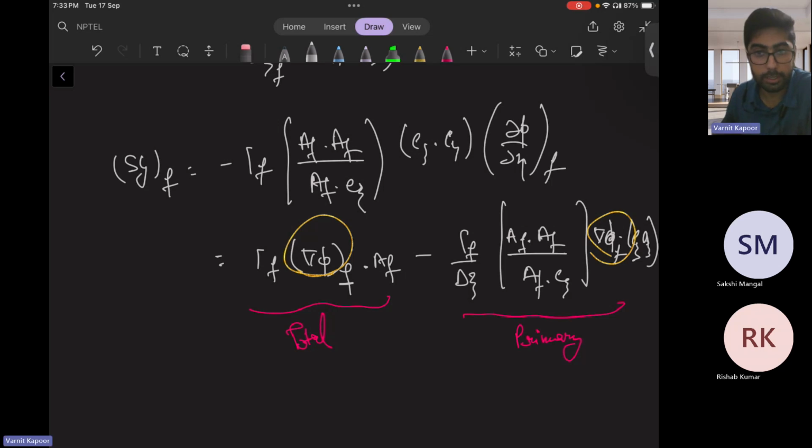How can we calculate this gradient? This is where grad phi is asking which scheme you will use to calculate it, and why we have to calculate it for use in the secondary gradient. One reason is that it is also used in many other contexts, you will see, for computation of gradients of phi using computers. Okay. So if you have an unstructured non-orthogonal mesh, for the calculation of the secondary gradient, how will you go ahead?